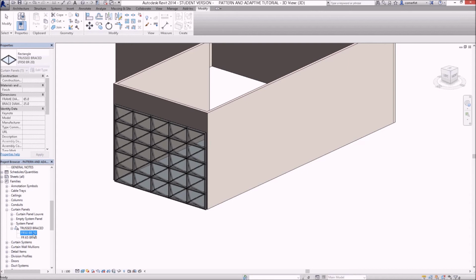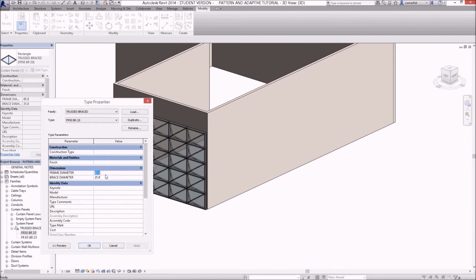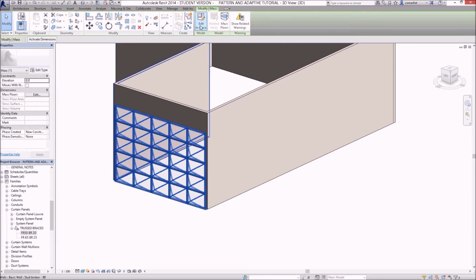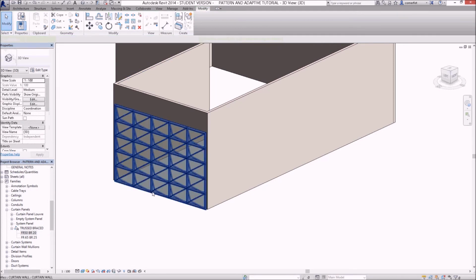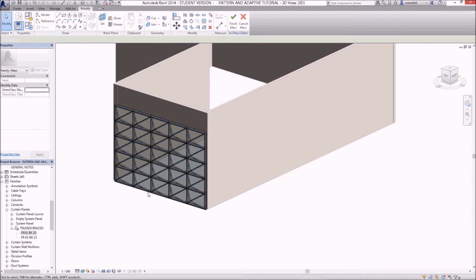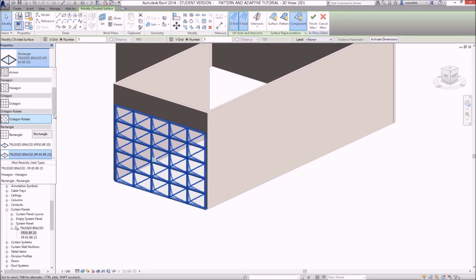And if I could now just go to a floor plan view, and I could pick it up and actually position it back where I really wanted it to go. So click that up and move it. Move it probably from that end. I'll just place it here for now. You can see how you could relocate it anywhere you wanted it to be. So facing on the inside, and I might just actually nudge that a little bit back inside the building like that. And there is my glass curtain wall that I've created.